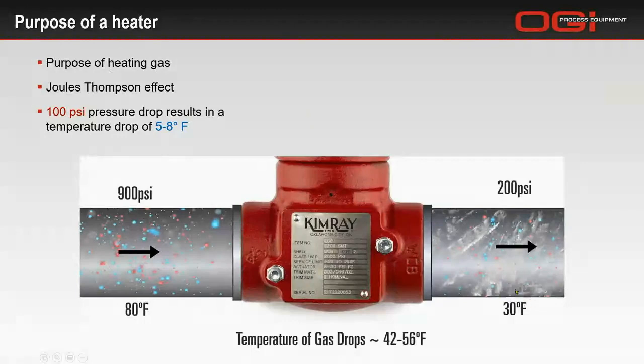The reason for this is if you look at your gas composition, you're going to find that it's not just natural gas. You're going to have propanes, butanes, and also elements of moisture. And if this isn't heated, you will run into freezing issues. So to overcome that, you simply heat the natural gas and to ensure that it remains above freezing temperature when it goes across the control valve.